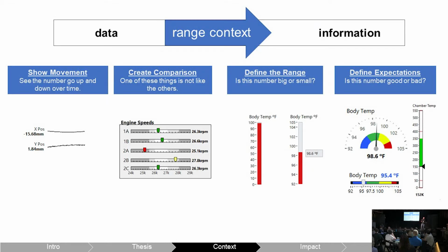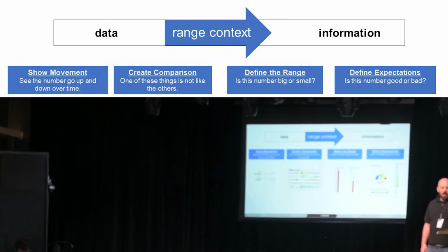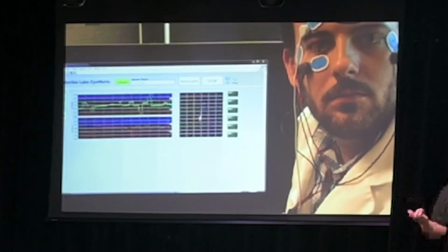Like, well, yeah, motor 2C, it should be around 26,000 RPM. If it gets up to 28.5K, that's fine. That's kind of optimal. But whatever you do, make sure it stays above 24K, because then the stuff gets bad. And I can tell you that whole story by looking at one little image. And now every operator who's looking at this user interface can give that context and can report those things and know when it's not bad enough that it's aborted the automated logic, but we should take a look at this, or it's looking suspicious.